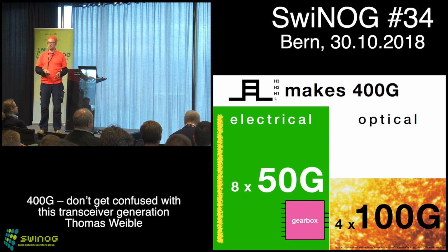So you can't stick to the current PCB material any longer. You need something like Teflon or ceramic for the PCB material. So it's way cheaper to just build a silicon chip, place it on the PCB, have the traces shorter, and do the high frequency stuff in the chip itself.